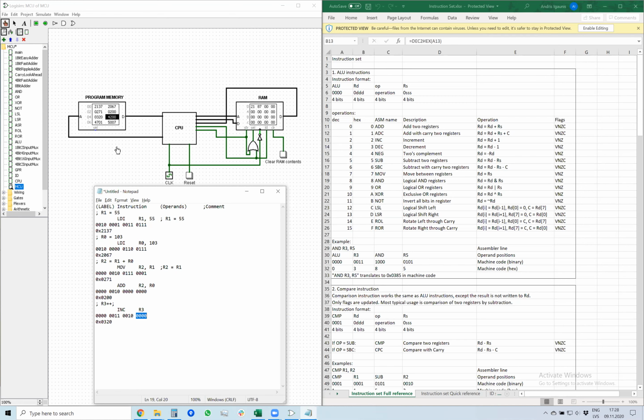If the signal is constant, almost no electricity is used. Only when you flip bits do you need energy. You need to recharge the field effect transistors to opposite values. So for example, if we wrote 2, 0, these bits wouldn't have to be changed. So you would save electricity. But of course, nobody really does that. That would be really complicated.